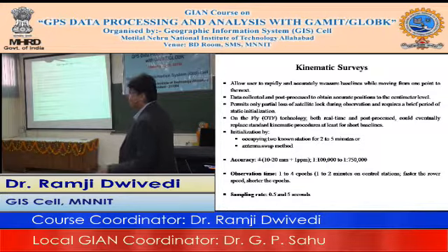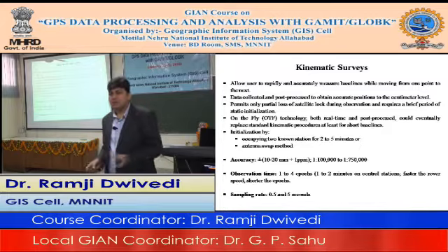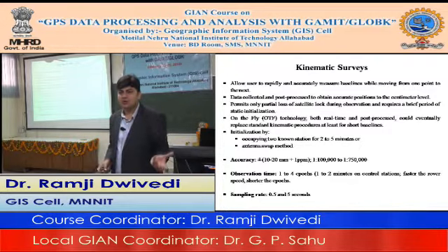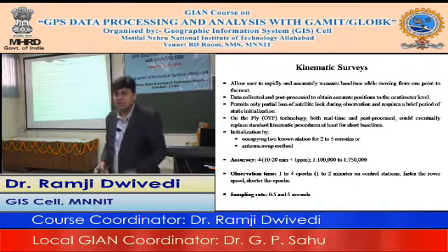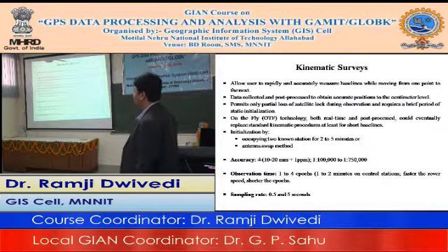The OTF technique, which is generally used, uses the lane combination, wide lane, as well as the ambiguity bias solution from the pseudo range measurements, and it computes the ambiguity. So OTF is the way. For occupying two known stations for 2 to 5 minutes, you could see the accuracy degraded from the previous rapid static also. It's 10 to 20 mm plus 1 ppm.